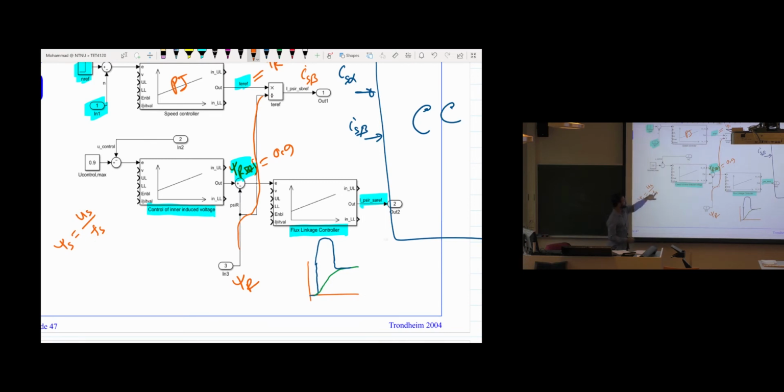But for speed, we want to have a much higher speed. If it is increased, then we see that this is going down. This is going down. So this means in that case we need to apply the field weakening. So what we do, we provide the voltage reference here, which is 0.9 per unit. And then there is the measured voltage from the DC, like the modulation index, which could be like 1, or we also said maybe 1.15. Then what is happening?